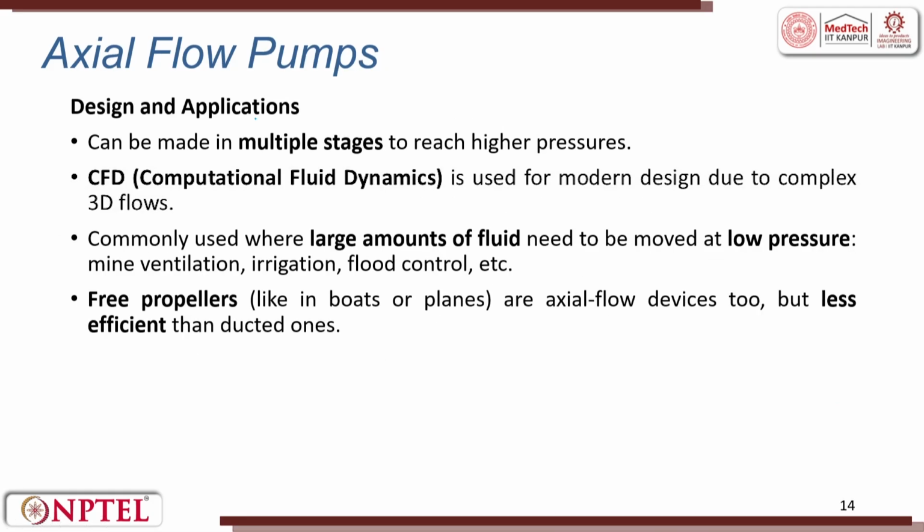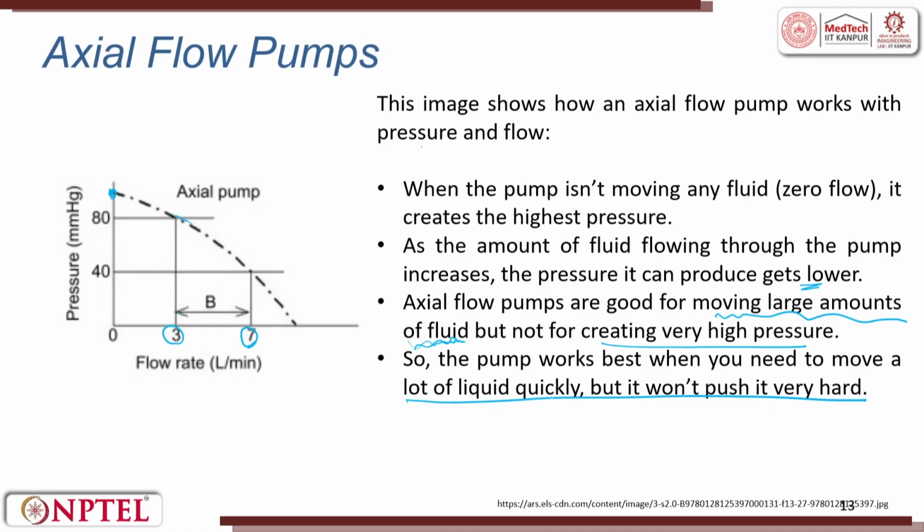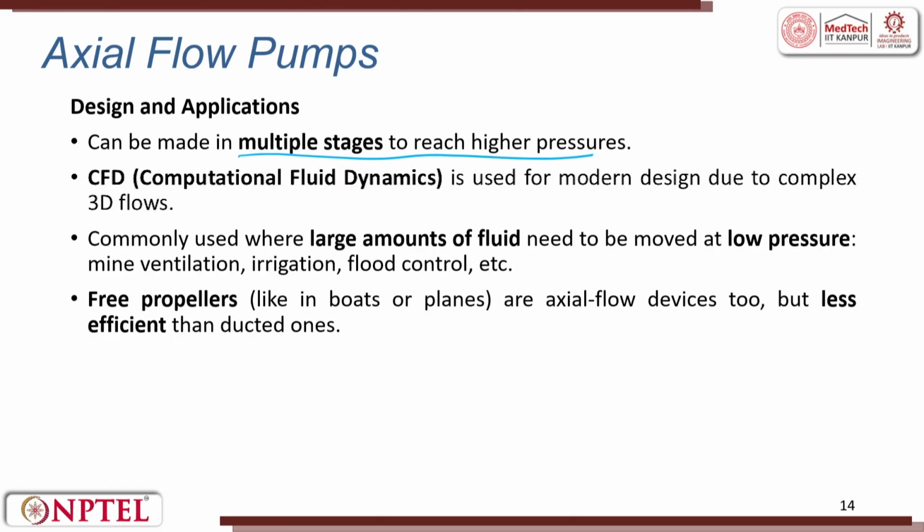So, on design and application, it can be made in multiple stages to reach a higher pressure. Why? Because here a large amount of liquid can be moved, but the pressure will be low. So, you add one more pump. In trains, when the engine cannot pull all the bogies, they put a double engine. Almost the same can be made in multi stages. So, it can be one more pump, or you can put multiple stages for increasing pressure.